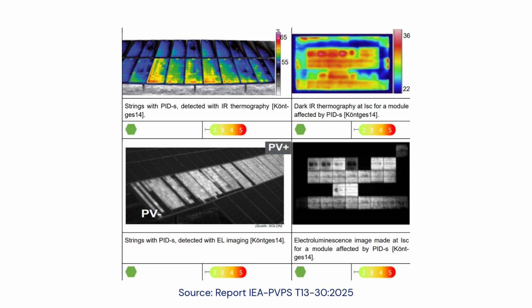Shunting degradation is also detectable by electroluminescence imaging, especially under low current bias, like 1/10 rated current, where the affected cells closer to the module frame show reduced luminescence. Shunting degradation causes a decreased shunt resistance, FF, and voltage in the IV curve, and is more noticeable under low light.